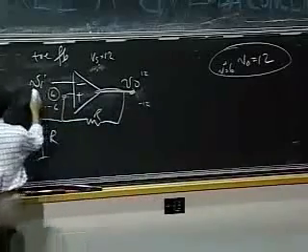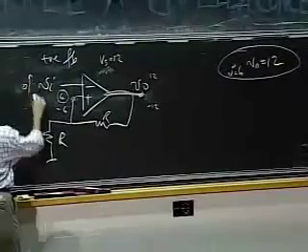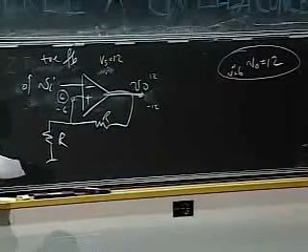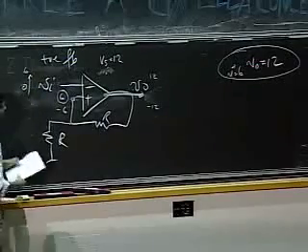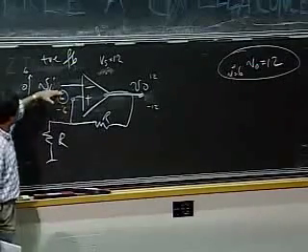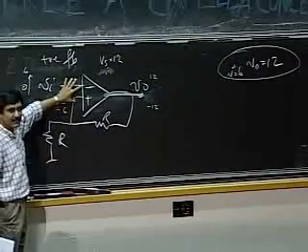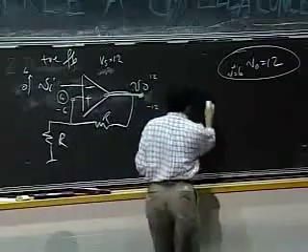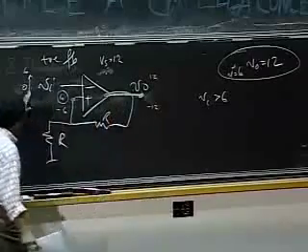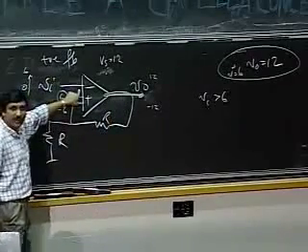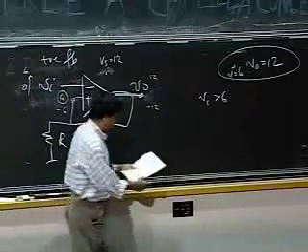Okay, now, this started off being 0. Let's say V in increases. As V in begins to increase, what happens? Well, nothing. Until V in reaches 6 volts. Since this is 6, V in has to go up to 6 volts, has to equal this voltage before I can flip the circuit. So what happens when V in is greater than 6 volts? If V in goes above 6, then I have more voltage on the negative terminal than the positive, and so the op amp flips its state,